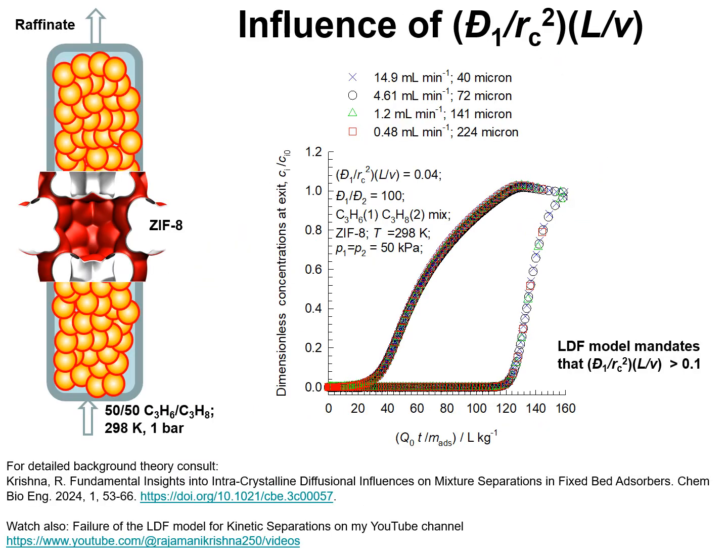We've established the optimum diffusional time constant and the optimum contact time for increasing the productivity of purified propane in the adsorption cycle. The product of the diffusional time constant in units of seconds to the -1 and the contact time in units of seconds, that is optimum, is 0.04. Now this optimum product of diffusion time constant and contact time can be achieved in many ways.